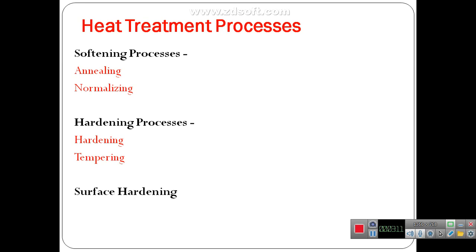Next one is tempering. When the hardening process hardens a steel specimen, it becomes brittle and has high residual stress. Tempering is an operation used to modify the properties of steel hardened by quenching for the purpose of increasing the usefulness. Tempering results in reduction of brittleness and removal of internal stress caused during the hardening. Steel must be tempered after the hardening process.